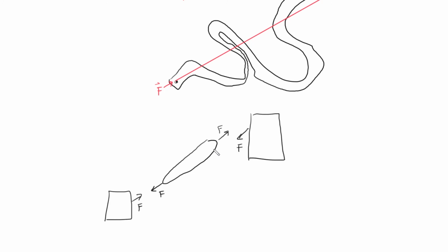So basically, this two force member doesn't have any moment acting upon it, and these forces are equal in magnitude but in opposite directions. So this is a valid two force diagram, and basically the force being applied on this part of the machine is being transferred to this other part of the machine. That's a very useful idea and concept that we can use later to solve problems.